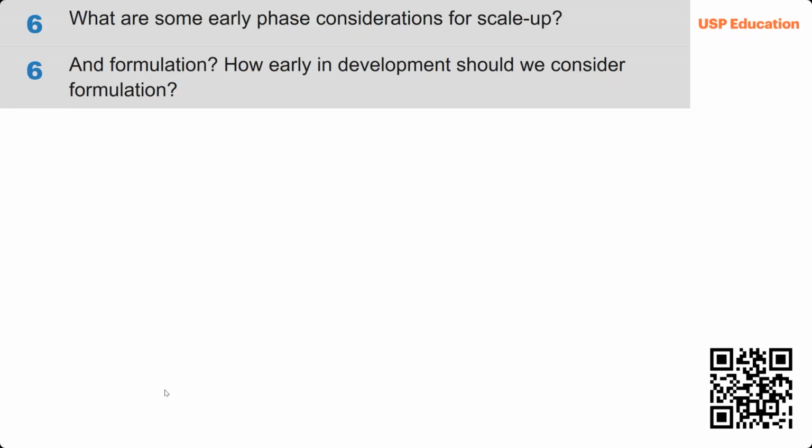A lot of vendors these days will offer quite a bit of characterization data on their bioreactor systems. And then it's really important to understand the shear forces that are generated at the impeller tip, and the overall considerations for dissolving air into the culture to make sure the cells are getting what they need, they're as productive as possible, and you're getting to the optical densities that you need to get the right antibody titer.